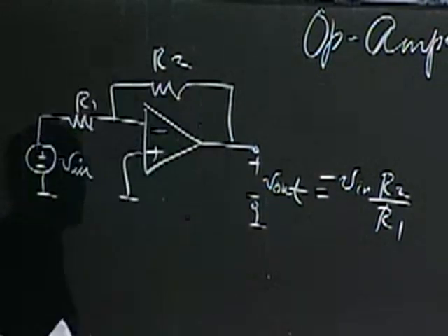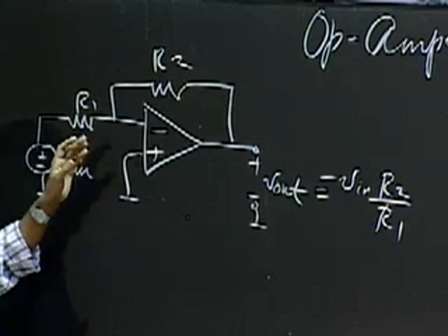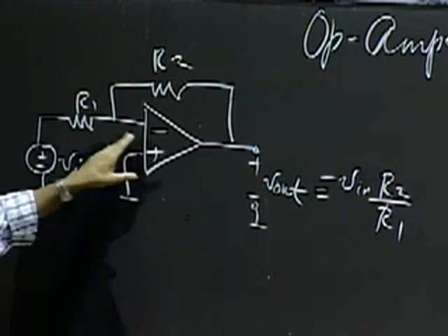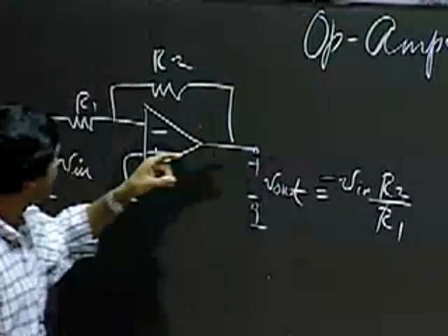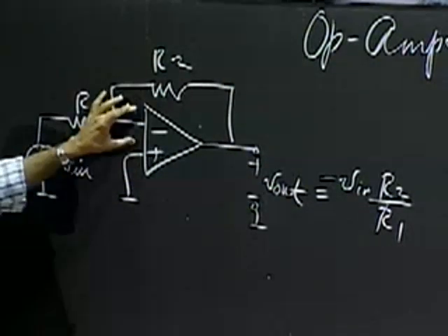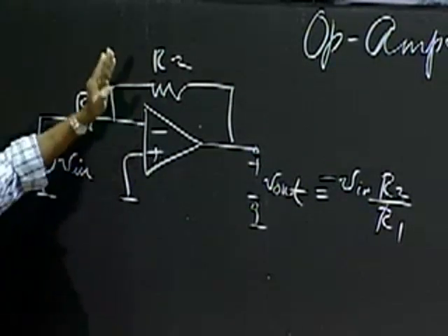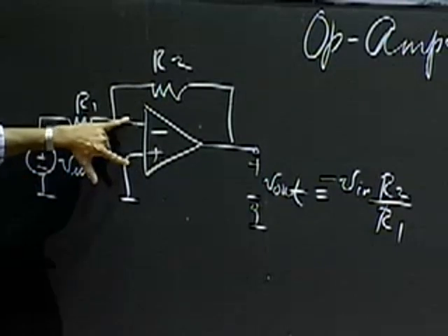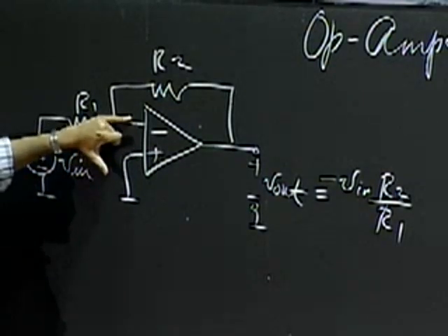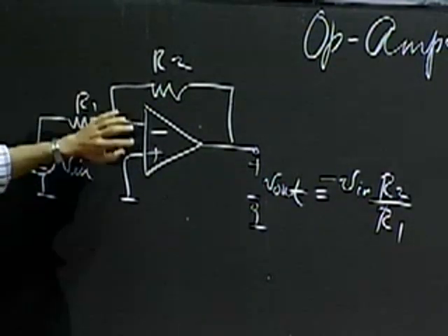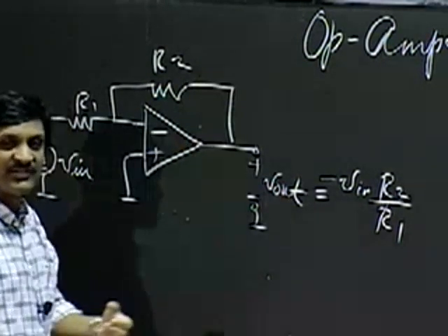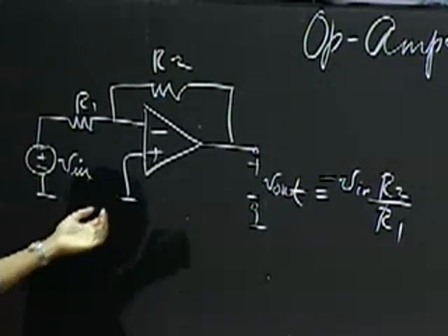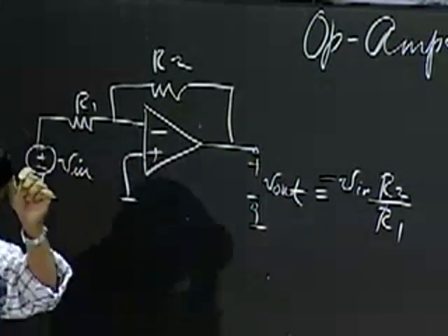So this is a negative feedback circuit because it's always fun to do the intuition thing and say that, look, if this voltage tends to go more positive than I care, then this negative input goes more positive than I care. If that goes more positive, then the negative input V minus becomes more positive than the plus input, which yanks the output down. Okay, so there's a nice counteracting force that keeps the output stable.